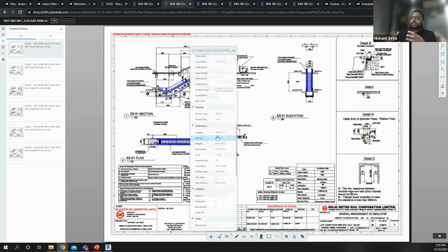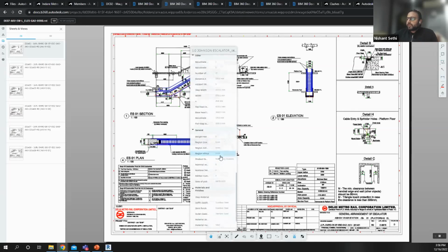So for reviewing a project, whenever a project gets submitted, whenever a project is with the contractor or who is viewing the sheets, they don't need to open Revit and go through all that hassle of loading all the worksets, loading all the models. They can just easily, in BIM 360, when they get the submission, view the sheets inside the model, show and see the properties, what material is there. Each and every small bit of the information of the properties which is there in Revit is easily visible here in BIM 360 only. This information is attached to the family and visible here to everyone.